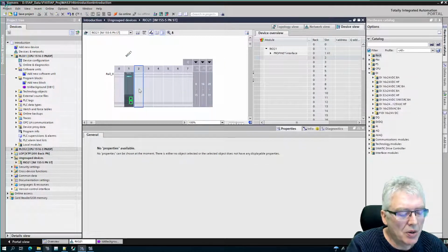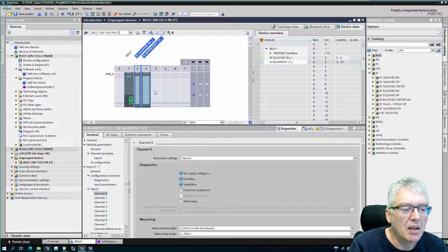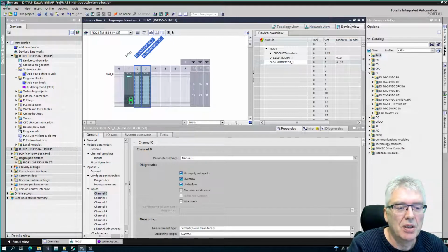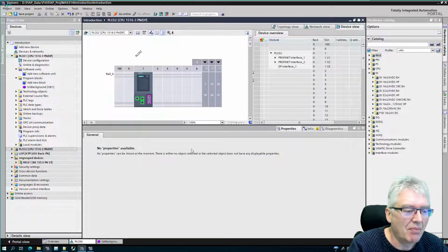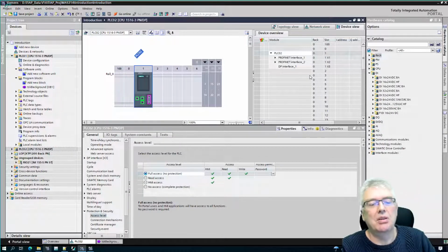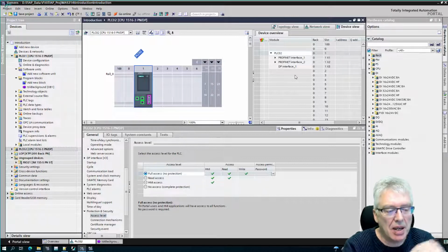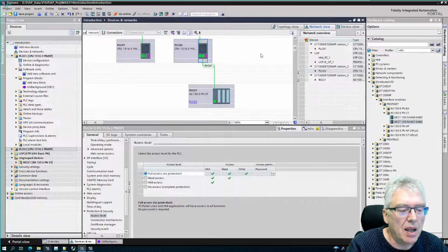and wait at the first one, Control V. So Control X is cut, Control V is paste. So what I did, hopefully I moved from PLC2 to my remote IO. So if I just go here and double click again, it's not much IO here. So I just moved them, cut and paste. I could have just copied and pasted, but then I would have the modules here. And okay, so now I've got IO here.